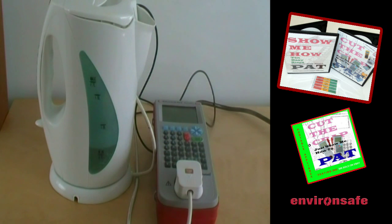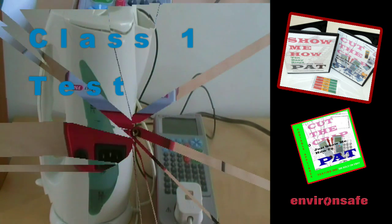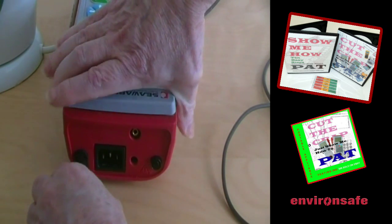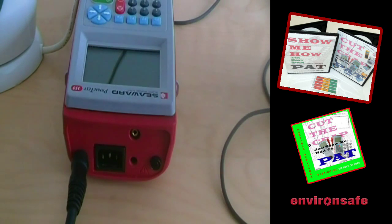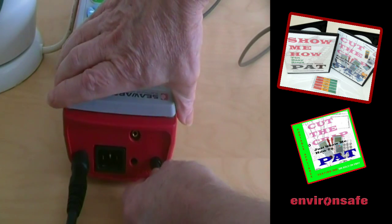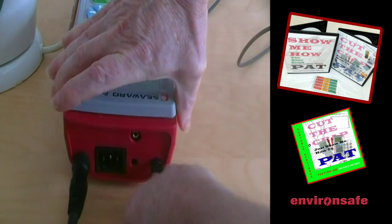How to conduct a full class 1 test on an electric kettle on the Primetest 350. Connect the supply lead to the power to the tester, and connect the earth bond lead to the tester.